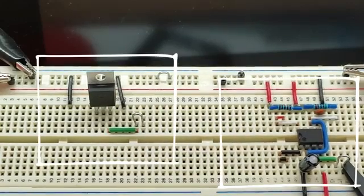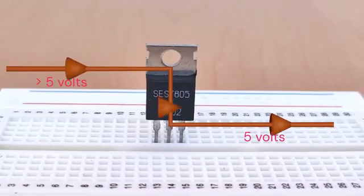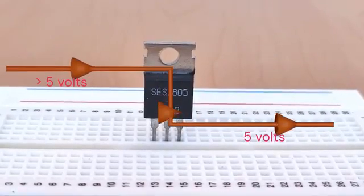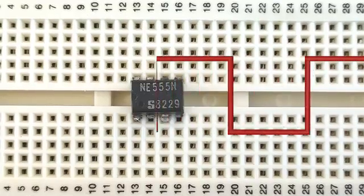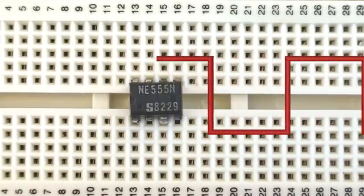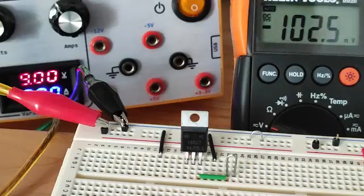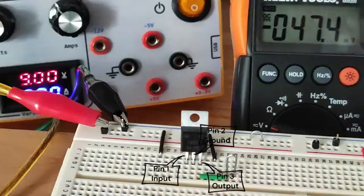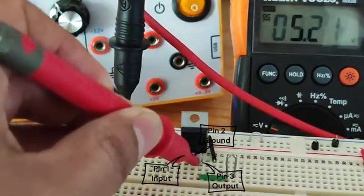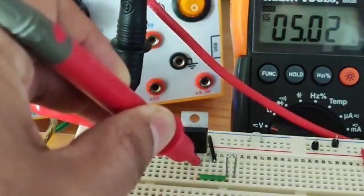These are two circuits to demonstrate the presence of noise. First, an LM7805 voltage regulator, which receives a voltage and stabilizes it to 5 volts DC. And with this 555 timer, generating a square wave at 123 Hz, which is considered low frequency. For the input of the regulator, I'm using a switching mode power supply adjusted at 9 volts DC. By looking into the output with the multimeter, everything appears normal, with an average output of 5 volts.